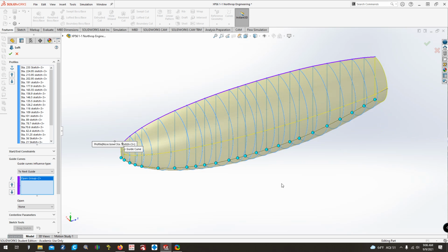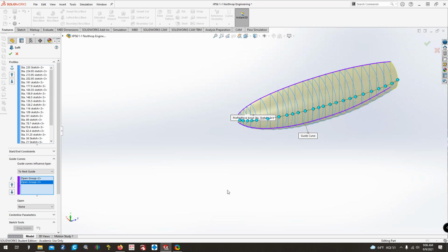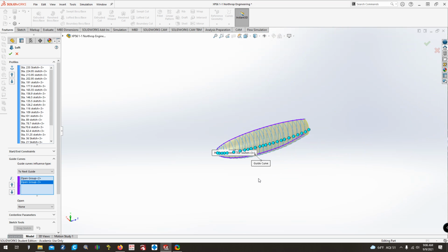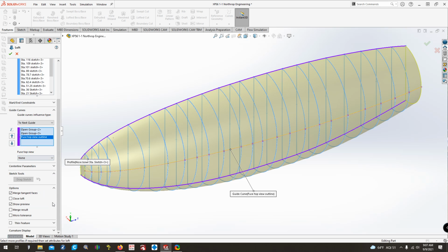We've got 3 profile outlines, so you want to use all of those outlines. The more of these outlines you can do, especially on really complex shapes, the better. So again, click the bottom one, click the extension that I put on it separately, click that. And as you'll see, especially with more complex shapes, the more guide curves you have in it, the more refined the shape becomes. And then here we will do our side profile. And there we go. We have all those 3.